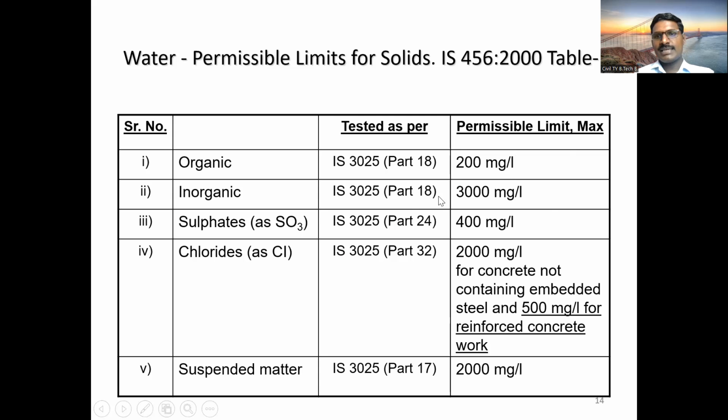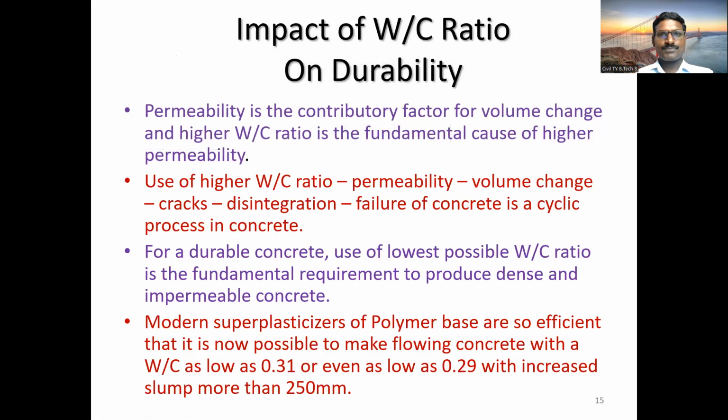The organic content is 200 mg per liter maximum, inorganic 3000 mg per liter maximum, sulfate and chloride 400 and 2000 mg per liter, and suspended matter 2000 mg per liter. So these are the requirements of standard water as per IS 456:2000.